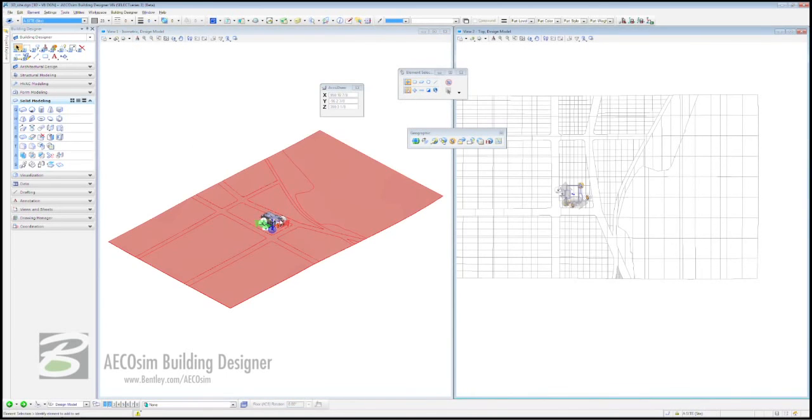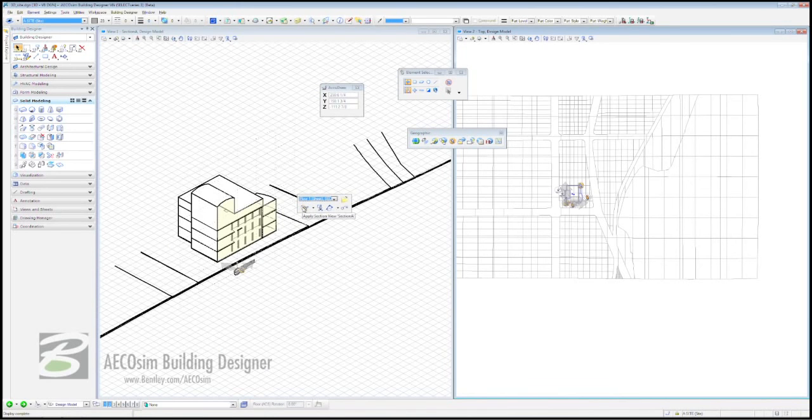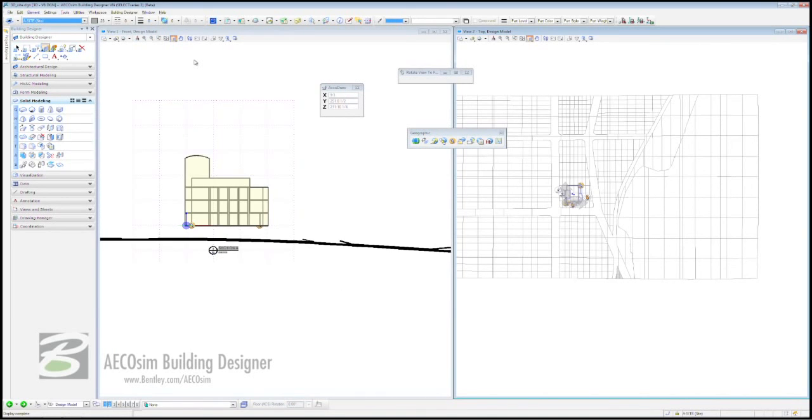And now if we zoom back into our structure, you can see that we still have those markers that show us where the cutting planes of our original sections are. So let's go and impose one of those sections, and this will help us coordinate, bringing together both our emerging 3D terrain model and our georeference file. Because now we can come up to our view navigation, rotate this to front, and you can see that our terrain is actually just sitting below our actual georeference file.